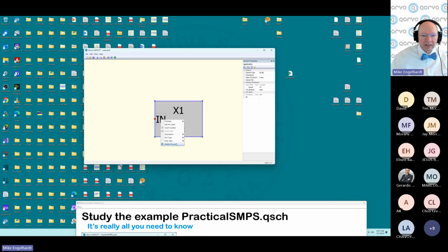Now you have to say the data type. If writing in C, I only ever use floating point because I would rather do any data conversions in my C code because it's more transparent what I'm doing. It's easier for me to know what I'm doing if I just do everything floating point. If you're doing Verilog, yeah, you want to use the fact that QSPICE can do all the data conversions for your I/O from analog to digital.